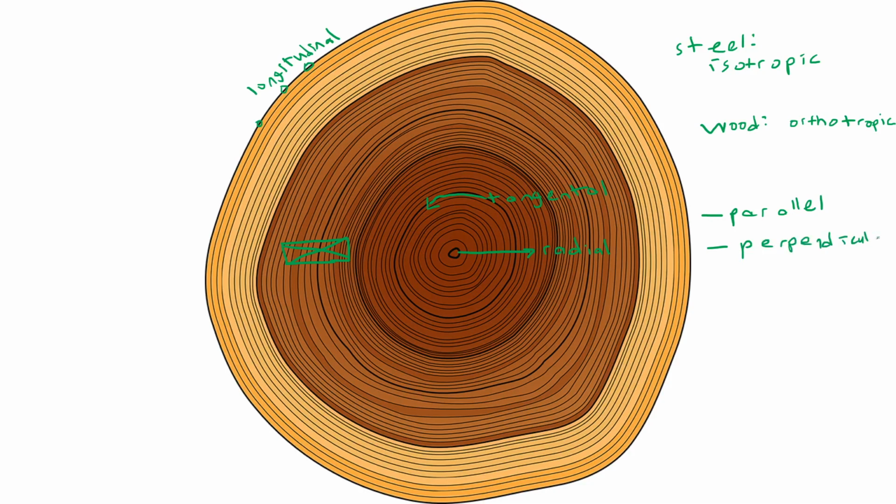Again, because longitudinal is the direction where the primary strength lies, we use one strength value for tension, compression, etc. that is parallel to the grain, and we use a different value for perpendicular to grain. Because actual boards are cut at varying angles in relation to the growth rings, in practical cases we can't effectively separate out tangential and radial directions, so instead we just group them together as perpendicular.